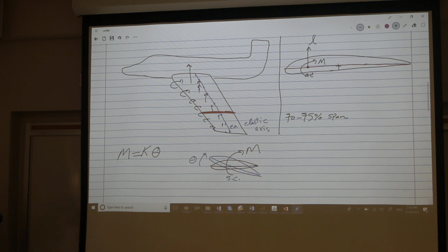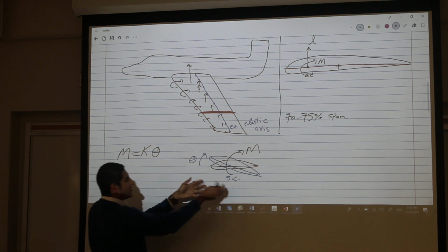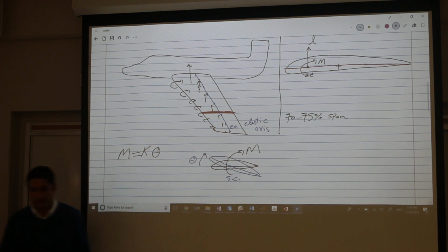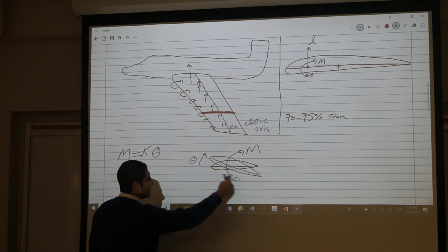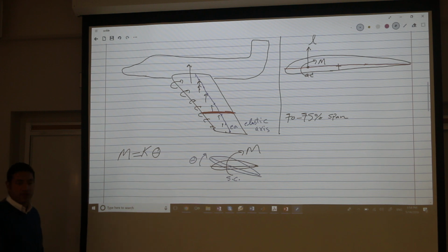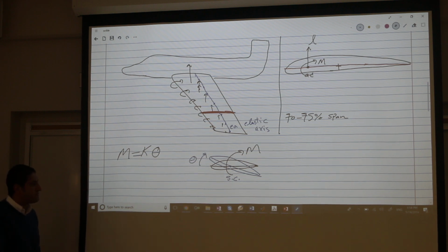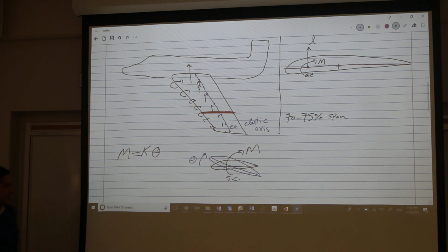So if you have a symmetric section, like a rectangle or something, the shear center is the geometric center, it's in the middle, but the airfoil is not a symmetric section. So determining the value of this is non-trivial, but you can use any off-the-shelf software like Nastran. It will tell you the shear center for a given airfoil. And I guess they are tabulated online. NACA 0012, you can go and look.